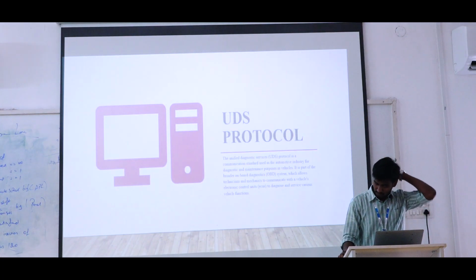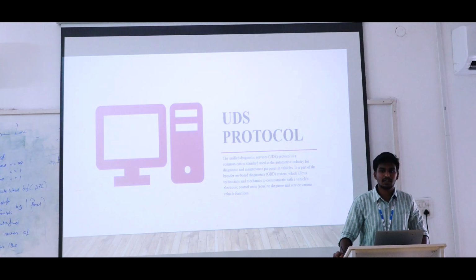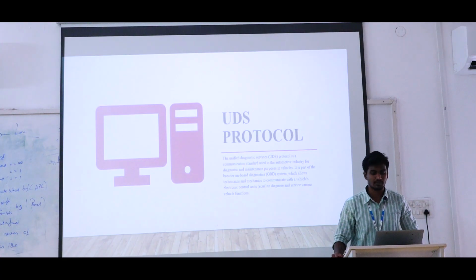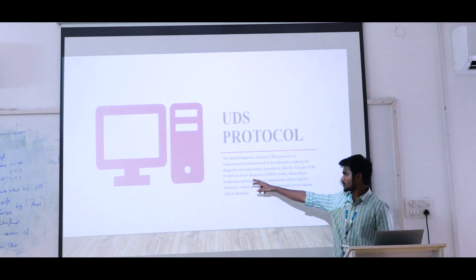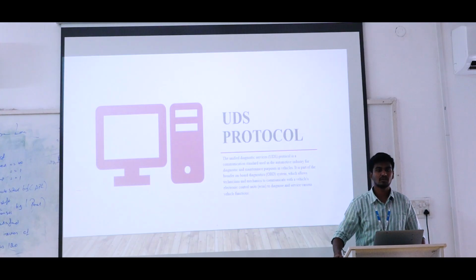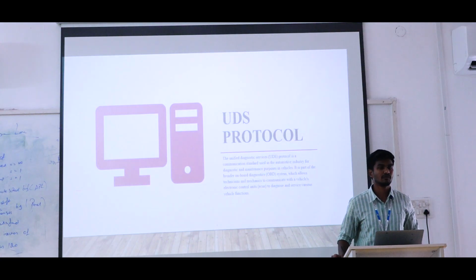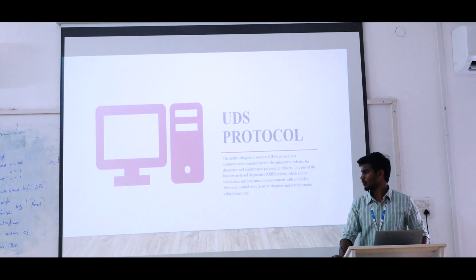Okay, so the UDS protocol. The UDS protocol is a communication standard protocol, with the ISO number 14229. It works with onboard diagnostics, which means the OBD port system. In all cars, not only cars, wherever we are working with ECUs, we will definitely get that final output source, called the OBD port, onboard diagnostics.